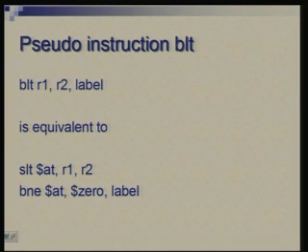We have already seen that register number 0 has a special role. Okay. So, by hardware, you cannot modify the contents of register 0, it always remains 0. AT or register number 1 is used by the assembler, it is more by convention. There is nothing which hardware does in this case.